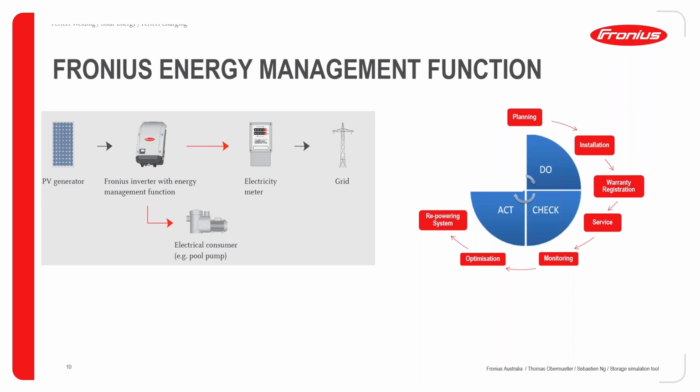So trying to use this excess of power, turning on loads like pool pumps and different, let's say, energy management systems. So with our Data Manager card, you have a digital output, which you can connect to an external relay where you can turn on and off a pool pump, practically any load that you want. So this is one of the first steps, and also it's standard on our inverter, so it comes with that.